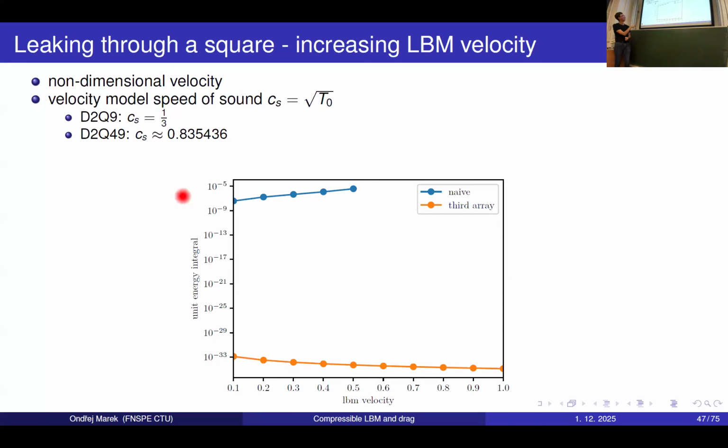That's also one of the reasons why this model does not have anything to do with the Mach number. It's just some variable used in the Lattice Boltzmann method, and this is because it's larger. That's also one of the reasons why the multi-speed models might be better to simulate the compressible flow, because usually LBM, the classical one, simulates weakly compressible flow.